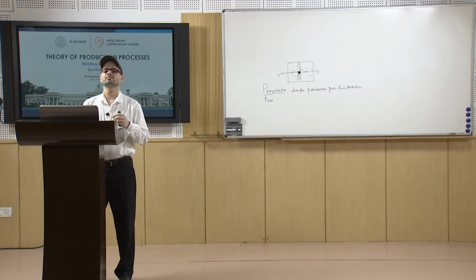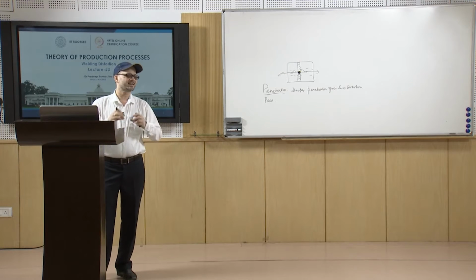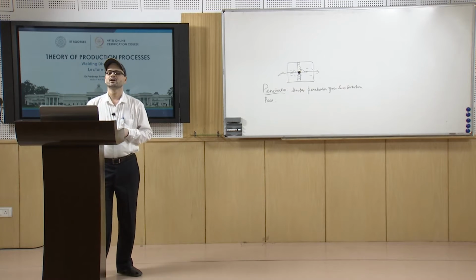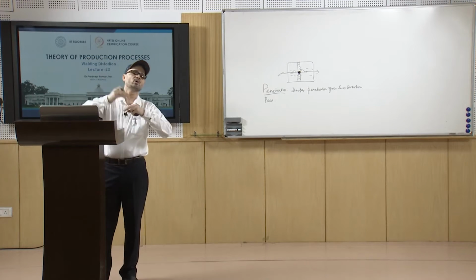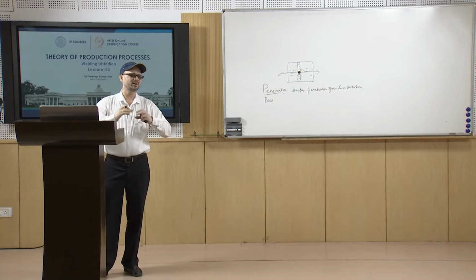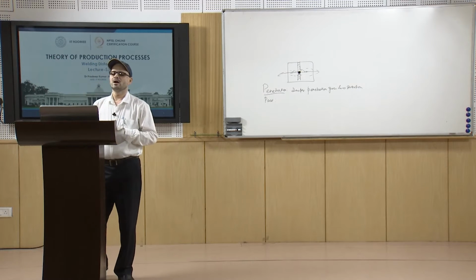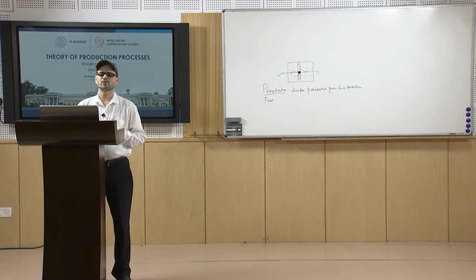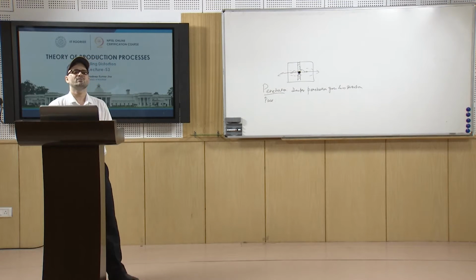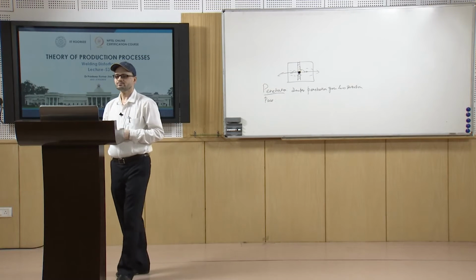Also the thickness of the plate. If the thickness of the plate is more, then the longitudinal shrinkage will be smaller, and with current and the length of the weld being more, the longitudinal shrinkage will be more. So, there is a correlation between this longitudinal shrinkage and these operating parameters for a certain type of butt weld. For butt welds, that is how it normally varies.